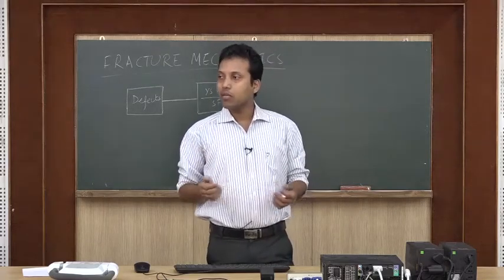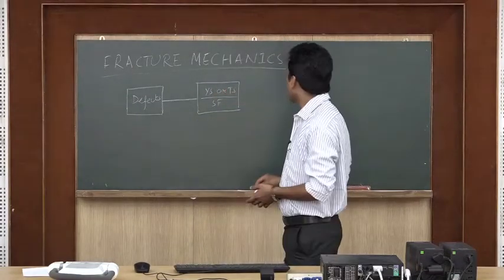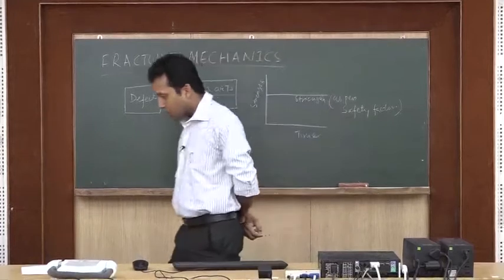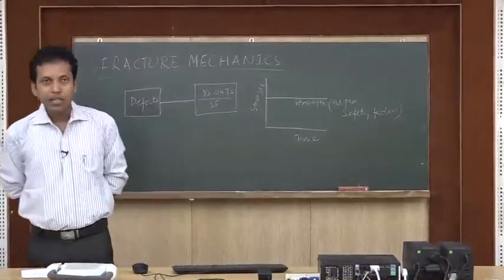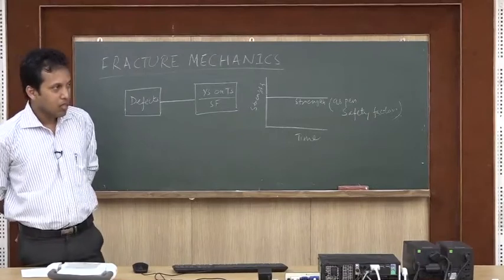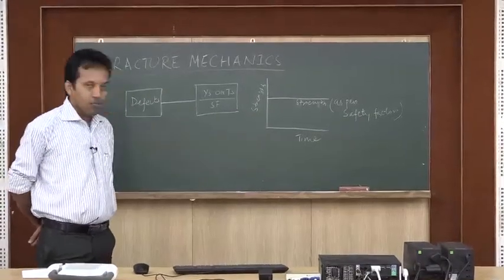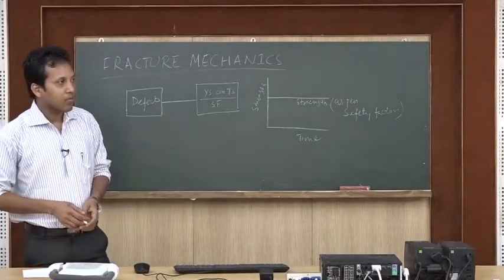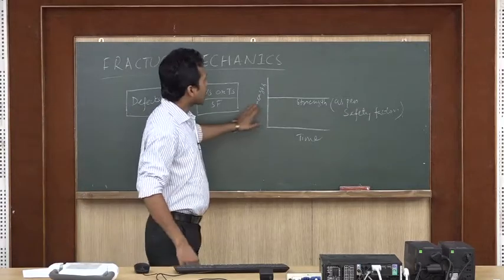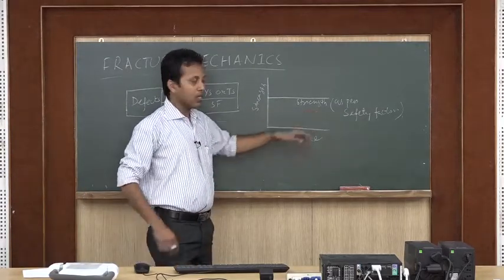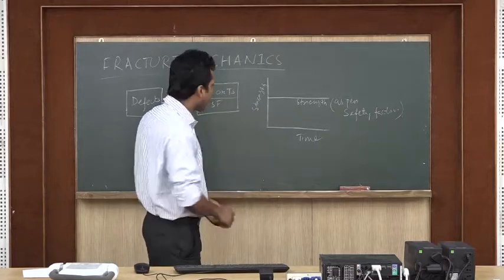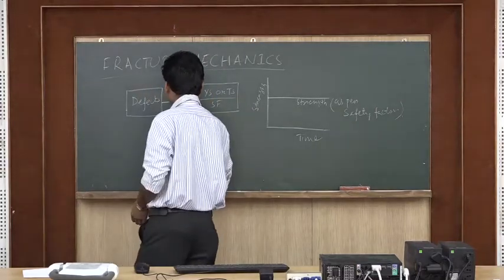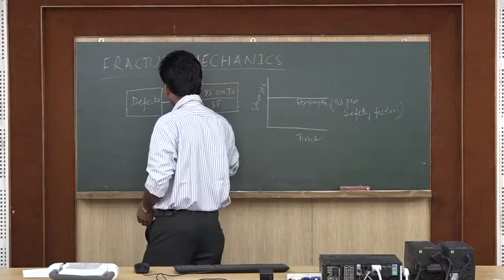Okay, so we have this idea, but even then, due to the presence of a crack, the upper limit of the stress for a material reduces. We can visualize that if in a material there is no crack, then with increasing time the strength level won't reduce, isn't it? For design purposes we have some particular strength level considering the safety factor, and with time the strength won't vary for the particular material. But if defects are present, what will happen?